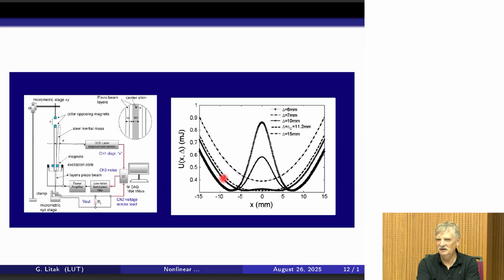And if it is not moving, but it's bent but not moving, then because we have an electrical circuit, it is not an open circuit, and the charge can flow. It would be the decay. So the charge would be balanced on the piezoelectric and the electrodes, and there would be no voltage on the resistor, the electrical resistor.